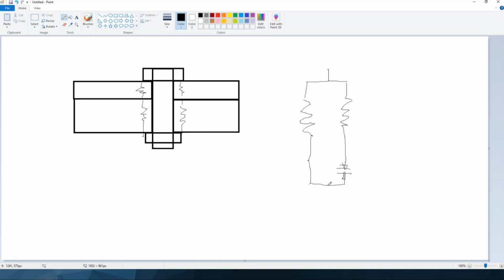Yes, that makes sense. Okay, now the problem is what happens if I now apply a load that's not enough to separate on that face as yet. So as I apply that load, this one, which happens to be in compression initially, is unloaded, and this one is loaded. So the compressive load decreases, the tensile load increases, but the actual change in load, because this is my bolt, depends on the ratio of the stiffness between these two.